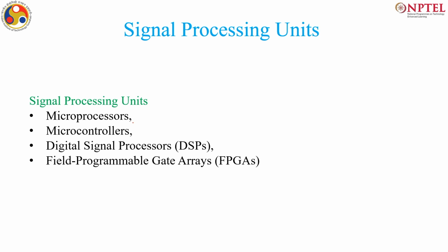That makes things like microprocessor, microcontroller and DSPs, where the main difference is that a microprocessor is a chip where you have your major operating units, like your arithmetic logic unit ALU, then control unit CU, some registers, some internal memories, etc. But you need external things like RAM and ROM to work with, and this is typically found in our computers, and you have to interface this, otherwise it will not work.